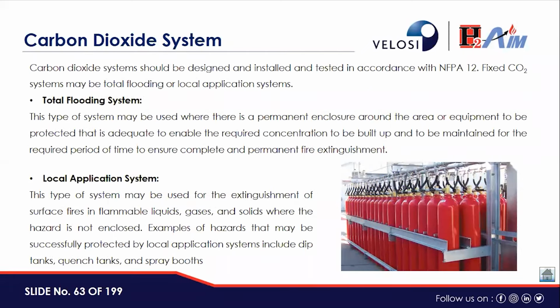Now, the carbon dioxide system. This carbon dioxide system should be designed, installed and tested in accordance with NFPA 12. Fixed CO2 systems may be total flooding or local application systems. Now, what is a total flooding system?